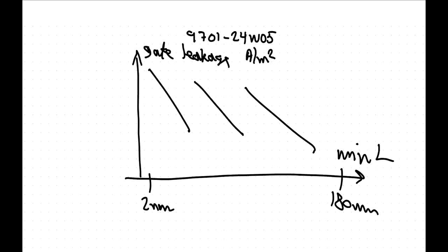It's a good question. Channel leakage is still significant, but gate leakage is also something you've got to take into account. I'm not prepared to commit to saying which one it is, because it also depends on transistor dimensions. If you have something that's really long with a high threshold voltage, but big, the gate leakage can be by far the biggest contributor. So you can't really say.